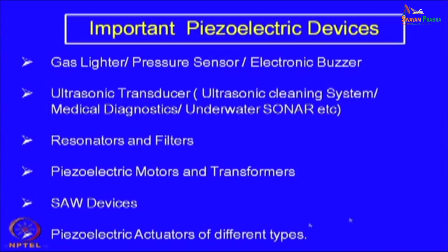It is the ultrasonic flaw detection system, and there you generate an ultrasonic wave, an ultrasonic signal, then let it transmit through the material, and it gets reflected from a crack or a grain boundary and so on, particularly if there is a pore or a flaw or crack.